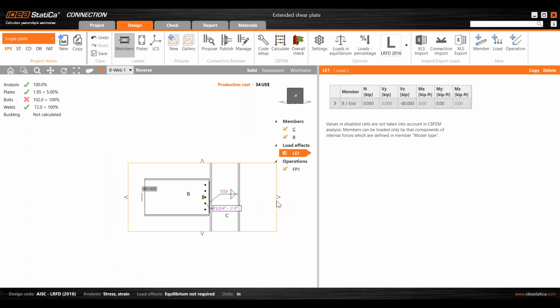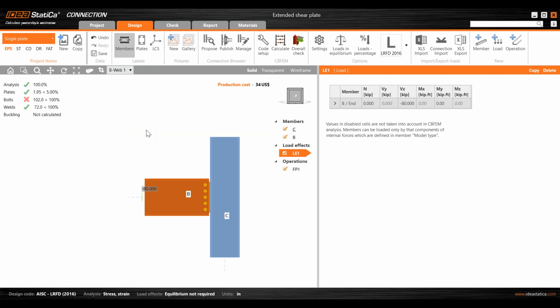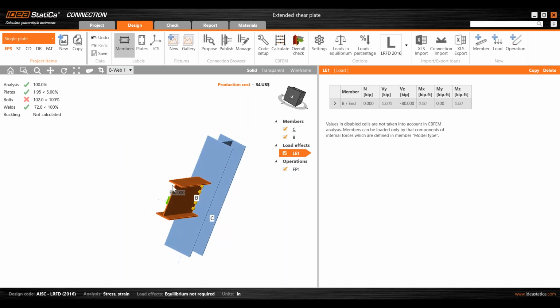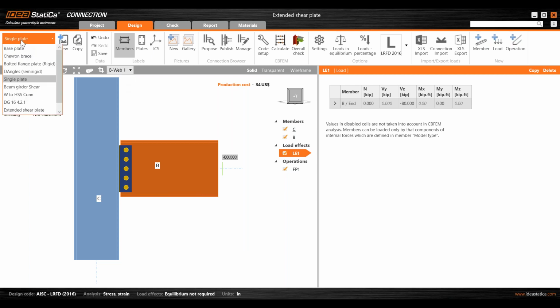Yep. There was a question about horizontal short slots. When we're using horizontal short slots in a standard shear tab, even with only 5 kip of axial loads, why does it require slip critical bolts? Yes, the software is not going to like it if there's no contact between the bolt and the edge of the hole, which would be the case if the load is in the direction of the hole, as in such a connection with horizontal short slots with axial loads. So the connection will not run for that reason. There needs to be contact, and slip critical bolts are the only way around this.